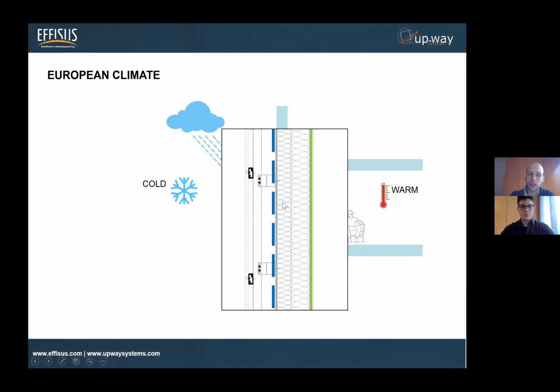And in fact, what could happen not only on this surface in here, but also within the insulation layer, is that our temperatures could cross the dew point line, and after that we would have the risk of condensation within the facade. So once we are blocking with the VCL just on the warmer side, we'll be avoiding those kinds of risk.